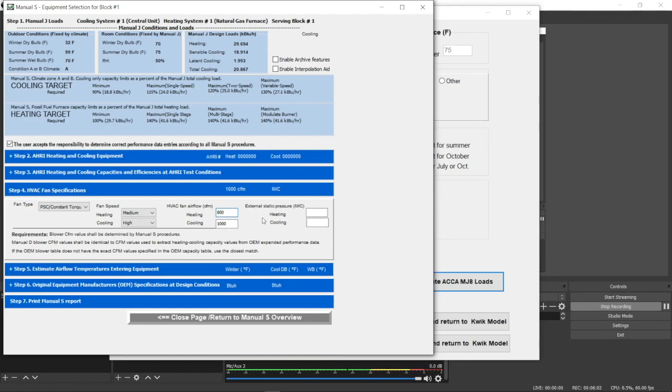This is just a first pass through. This is a fairly iterative process. I'm going to start with just some default assumptions, 400 CFM per ton, so many BTUs per ton, sensible, and then I'm going to go through once, and then I'm going to come back and check it. And then what I would normally do is start looking at more specific actual pieces of equipment and start plugging those numbers in and fine-tuning things as I go.